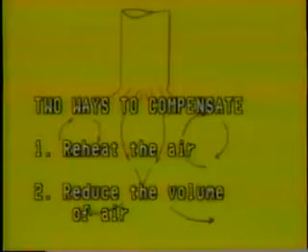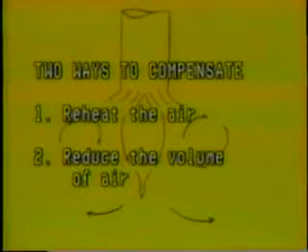As true of many systems, the constant volume system just described was sized with a 20% peak load factor. Generally, this peak load condition will exist less than 10% of the time. Therefore, the system will be extracting an excess of 10,370 BTUs per hour from the space. As a result, the space temperature will drop. There are two ways to compensate for this space temperature drop. One, reheat the air, or two, reduce the volume, CFM, of the air.